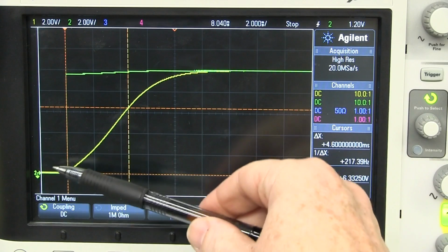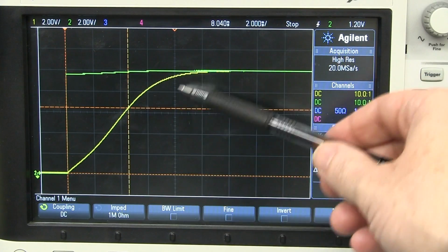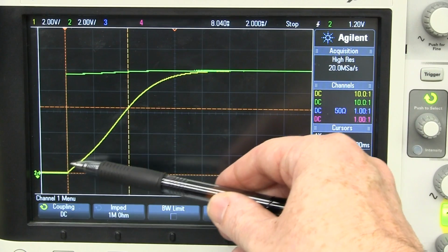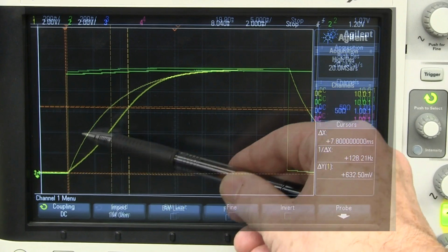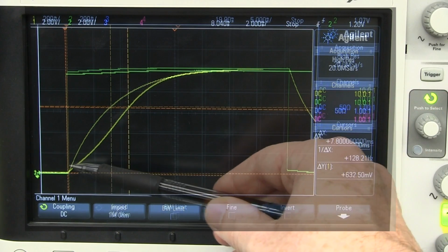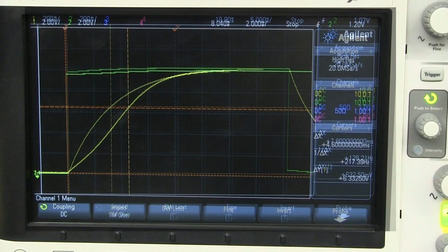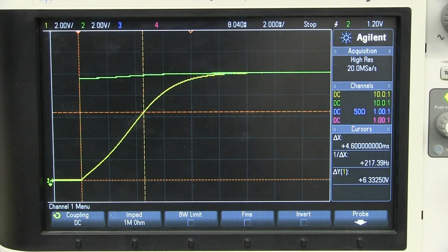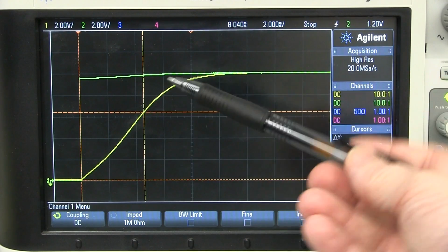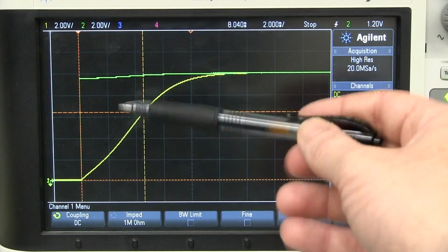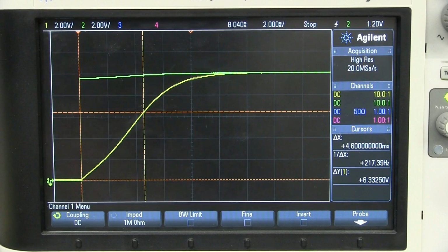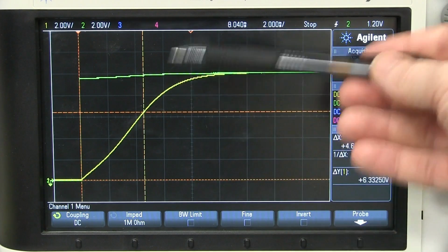Pretty horrid, but look at this. The wave shape, the charging waveform has actually changed. It is not that sort of rapid rise and then the decay like that. It sort of goes up like this and then decays. Totally different to what we saw before. So these Y5V caps are absolutely horrible, and there's some weird physics going on here based on the dielectric and the construction of these Y5V capacitors. They're nothing like those X7Rs that we got before, or even like this same Y5V but down at 1 volt. All we've done is now change it to 10 volts.